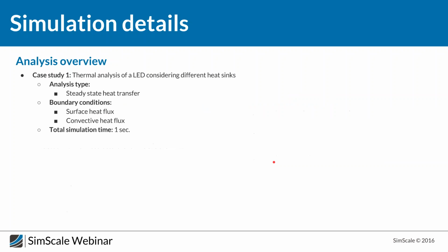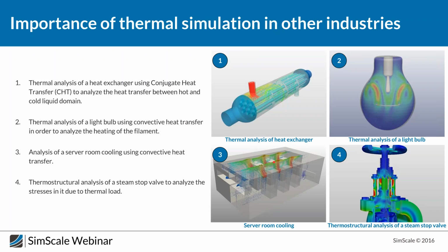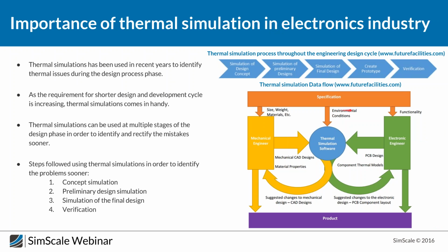If we go to the flow chart of the model here, the environmental condition, as I have referred to, is the conditions from the environment. For example, in the case of the LED, the environment would be how the heat sink surfaces are touching the outside air. Is the outside air static, like natural convection, or do you actually have a fan which is taking out the heat, or is the air flowing over the heat sink?